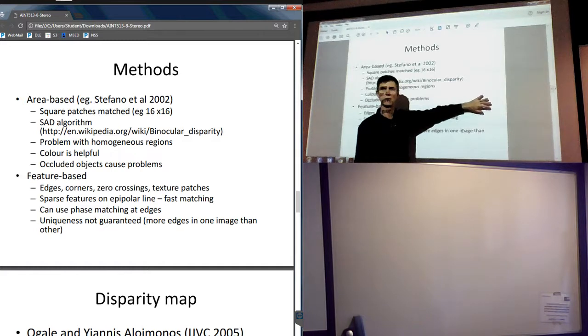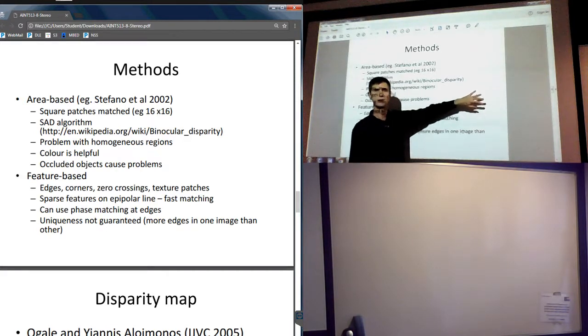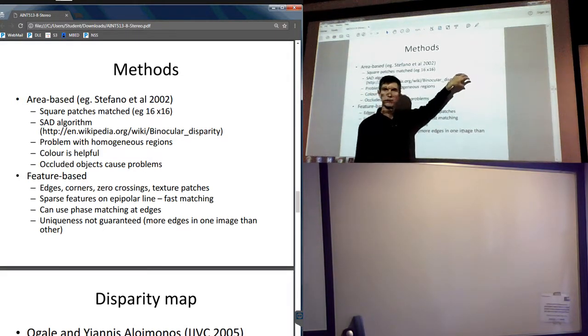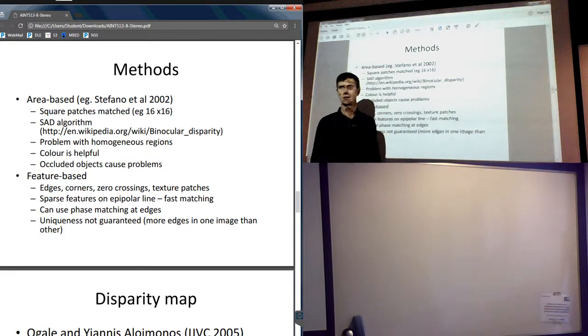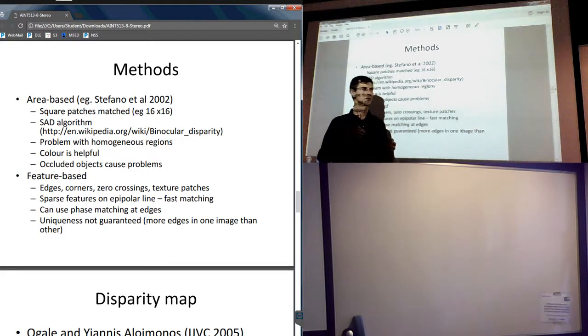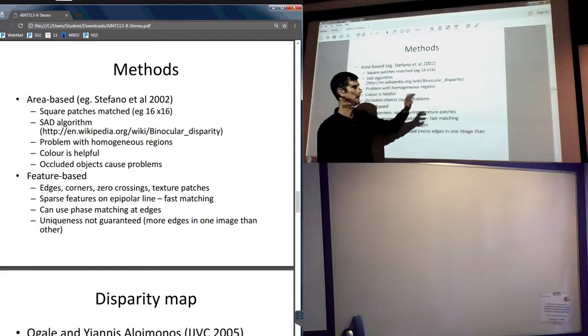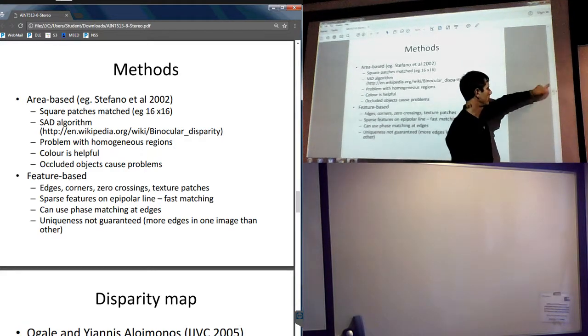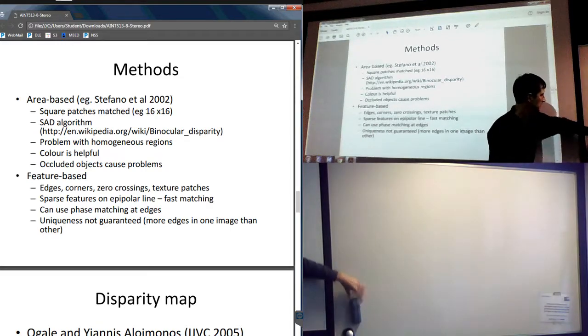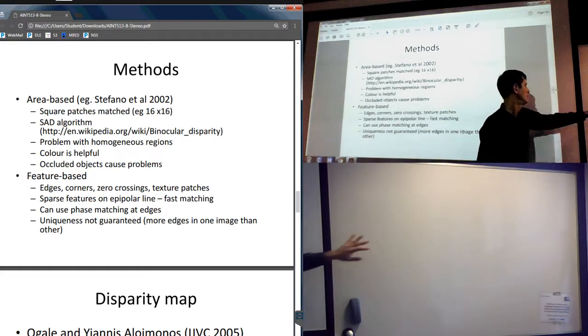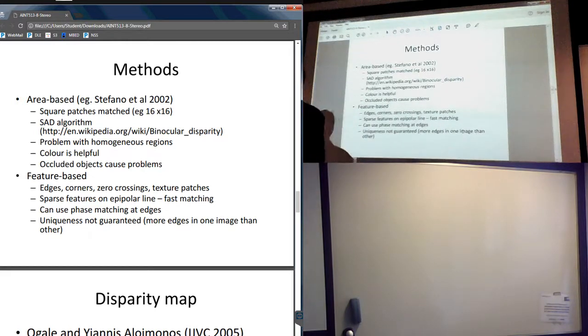So stereo depth, passive stereo depth, only works if you have textural differences in the patches in the picture in the field of view. So trying to do a stereo depth of this wall here will give you strong answers where you have features, and no answers, so holes, where there is uniformity. This then leads to lots of gaps in your data, so stereo pictures look quite noisy.